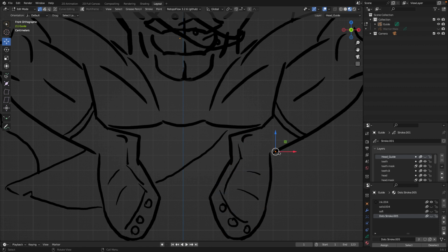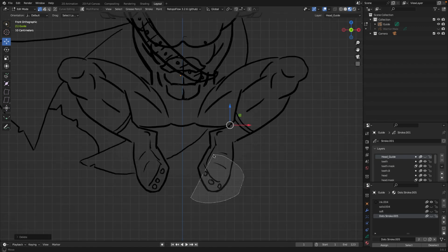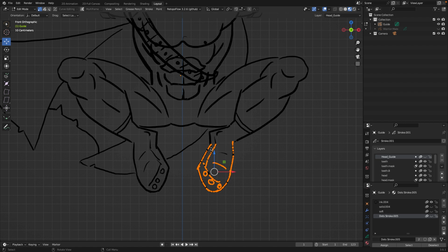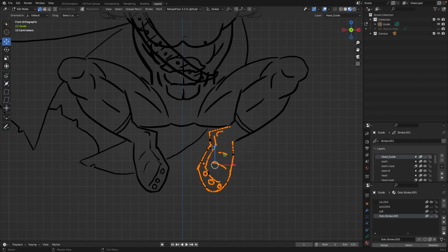We're gonna take this here, and press X and delete. We're gonna do the same thing over here, X and delete. The reason that we're doing this, now we can select this again, press L, and it will not select those parts that we don't want, since this part is already separated. See that? That's another way of doing it.